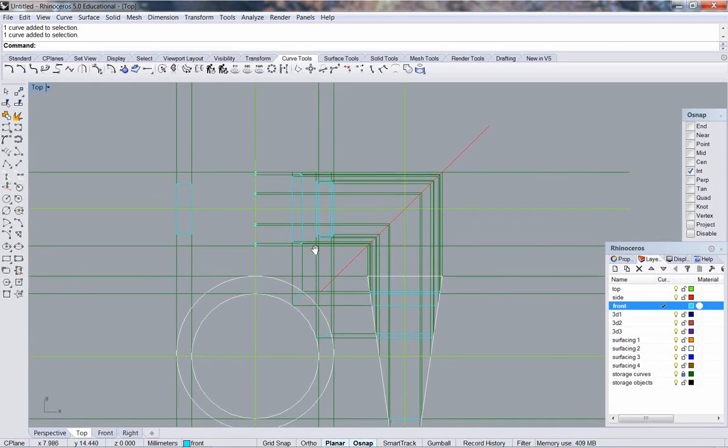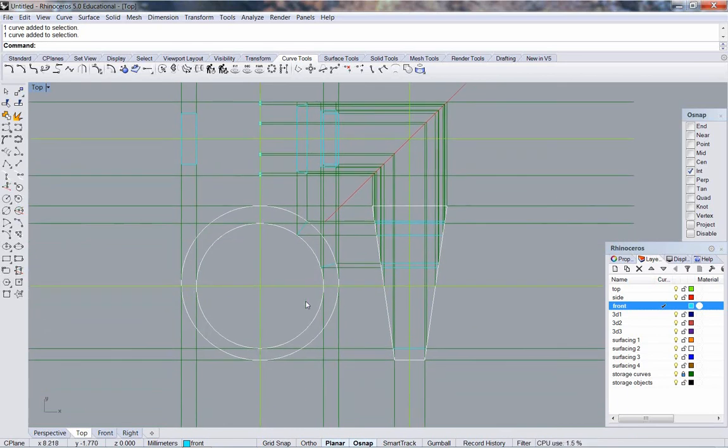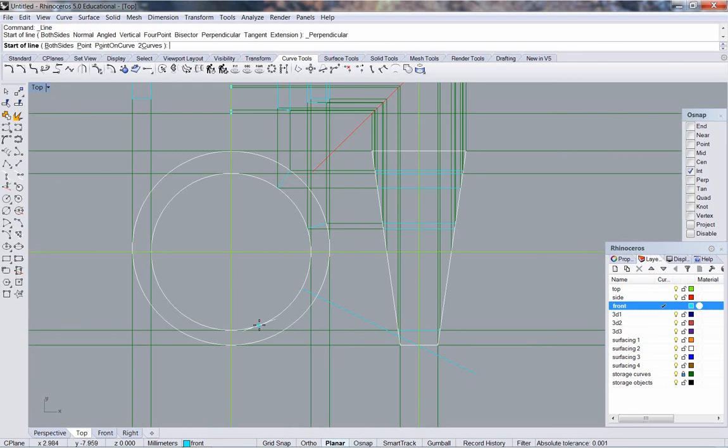Okay. I'm going to do my lower two cross sections. Going to pull this one a little ways farther over. Hold down Alt key, deactivate any of my object snaps. And the next one will be quite close to the center line. Trim those off.